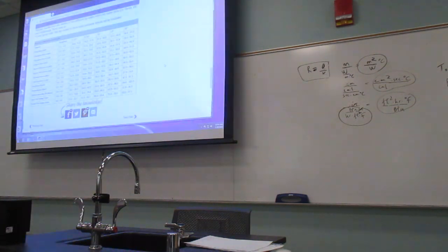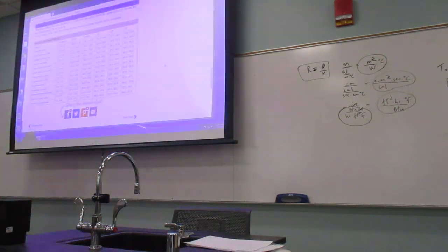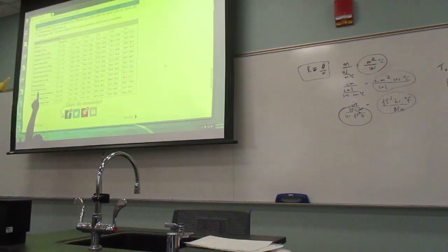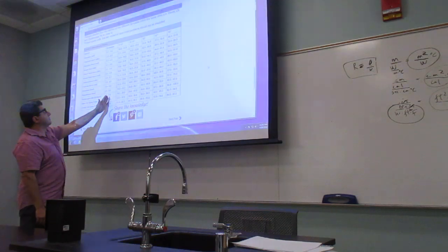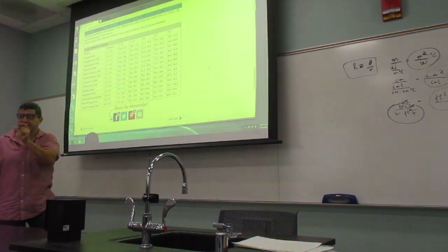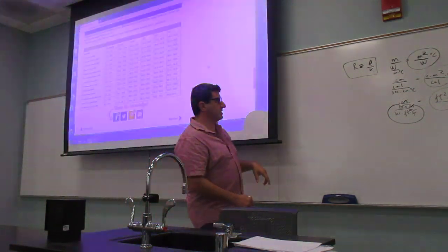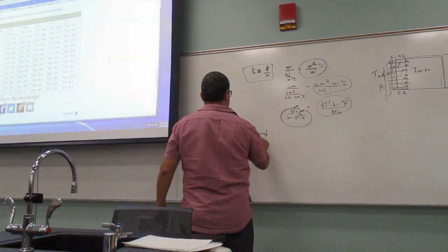So the R value, how is it given? Blown fiberglass, the R value that you put in the walls is different than the attic. The wall fiberglass is a better fiberglass, bigger R value, right? Now, how are they given? This first column is in units of some number over inches. That means per inch of the material, that's the R value, do you see? So what they've done is they've said R value of fiberglass.